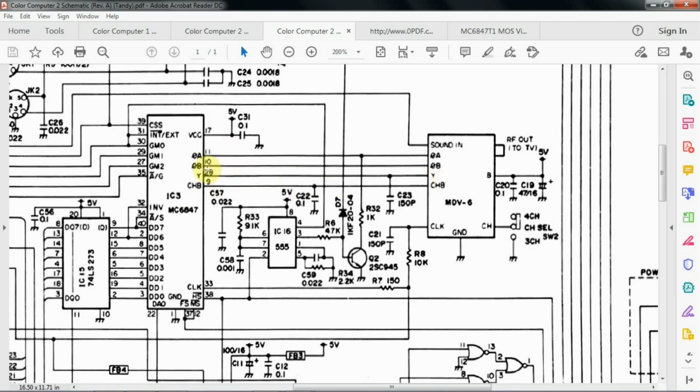But the image can be recreated from the Y, which again is the overall luminance and synchronization information, which is enough to actually form a black and white image, plus the A and the B color information, or the chrominance. So luminance plus chrominance make up the entire video. And in fact, S-Video is 2 signals rather than 3.